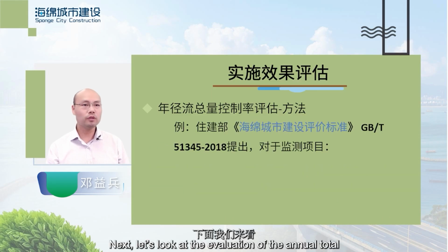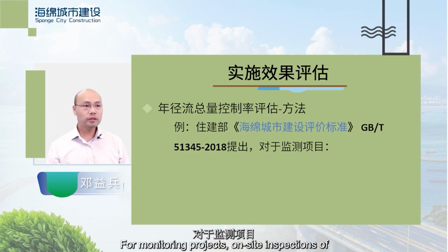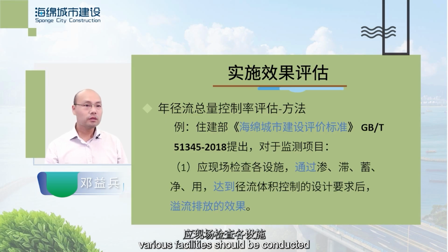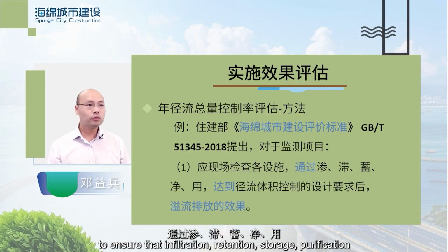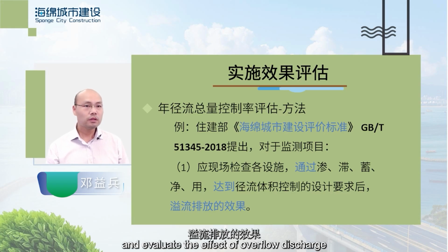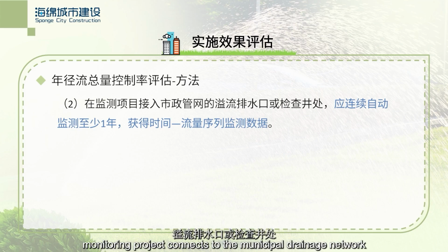Next, let us look at the evaluation of the annual total runoff control rate for monitoring projects. For monitoring projects, on-site inspections of various facilities should be conducted to ensure that infiltration, retention, storage, purification, and usage meet the design requirements for runoff volume control, and evaluate the effect of overflow discharge at the overflow discharge point or inspection well where the monitoring project connects to the municipal drainage network.